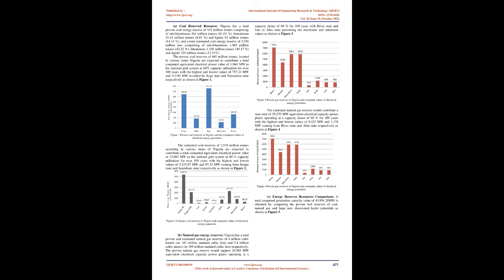Transmission line voltage decreases when heavily loaded and increases when lightly loaded. This is line loadability. The line loading limits are the thermal limits, the voltage drop limit, and the steady state stability limit. The existing power network must be transformed and expanded from radial to ring because of the high power losses associated with it, and this helped to maintain acceptable or allowable voltage violation drop of 5% of nominal value in the system. Nigeria has sufficient reserved energy resources of coal, natural gas, and newly discovered hydro potentials that can serve as an input to all economic activities.